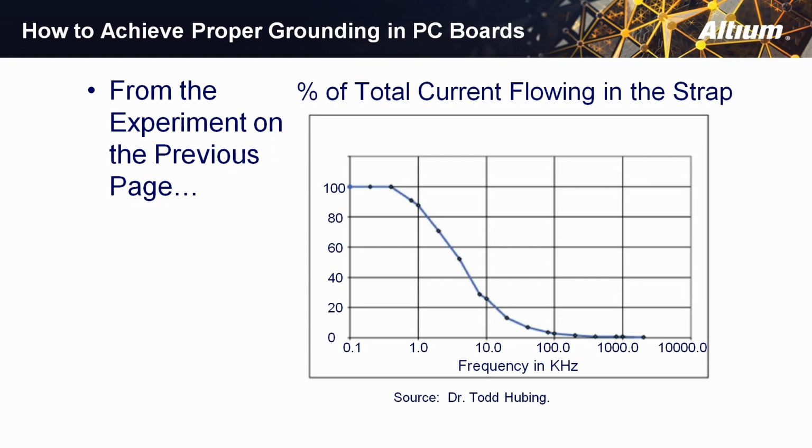And it really is not associated with the clock. So keep that in mind. So frequency today in digital circuits, regardless of clock, is measured in the hundreds of megahertz and up. Everything you use in the digital domain, even the slow microcontrollers, have rise time frequencies in the order of 100 megahertz or more. So everything you're doing is high frequency.